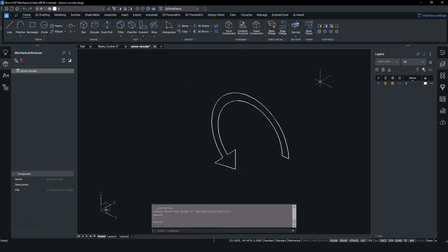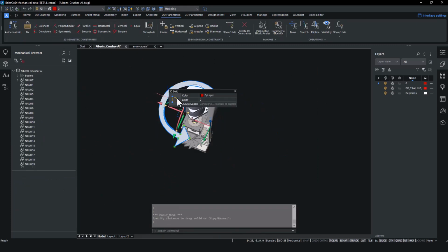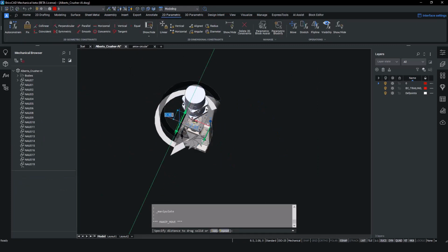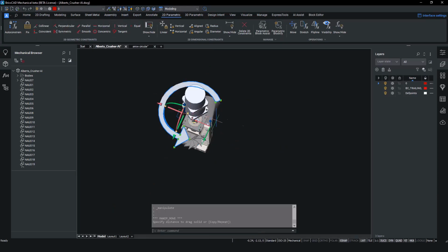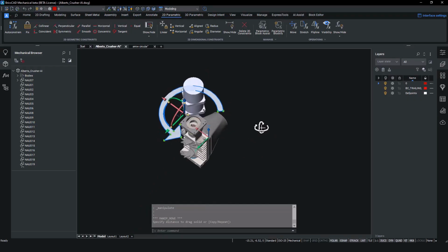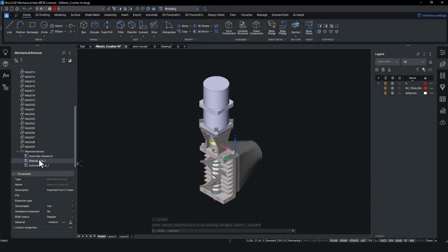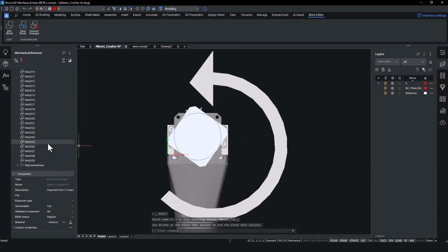Open the DWG of the arrow. Now select and copy the annotation of the arrow DWG. Now we paste this into the step and orientate it correctly. With this annotation, we're highlighting that in this step, the motor unit must be rotated into place. Returning to the sequence, we can see the arrow exists in step 2 now.